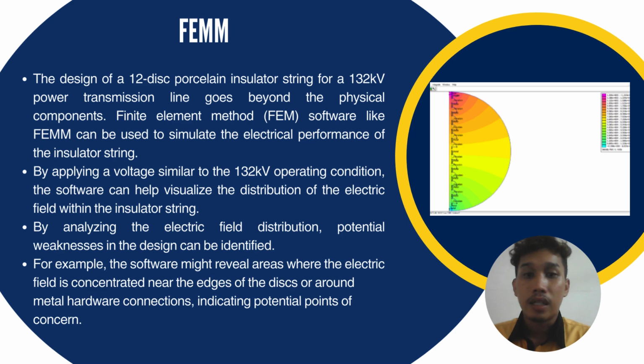By analyzing the electric field distribution, potential weaknesses in the design can be identified. For example, the software might reveal areas where the electric field is concentrated near the edges of the disc or around metal hardware connections, indicating potential points of concern.